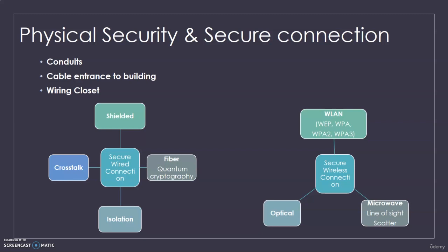Anytime I send an electric signal down a cable, we will create an electromagnetic field around the cable. This is why we twist our cables, and we often call them either unshielded or shielded twisted pair, so that we are able to break up that effect of electromagnetic crosstalk and interference between the various wires of a cable.